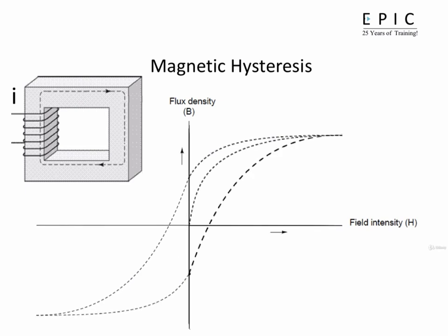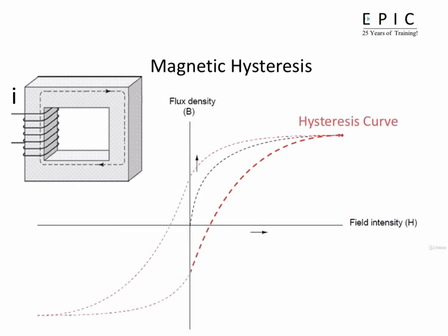If we reapply power in the positive direction again, we should see the flux density reach its prior peak in the upper right-hand corner of the graph again. This S-shaped curve traced by these steps forms what is called the hysteresis curve of a ferromagnetic material for a given set of field intensity extremes.